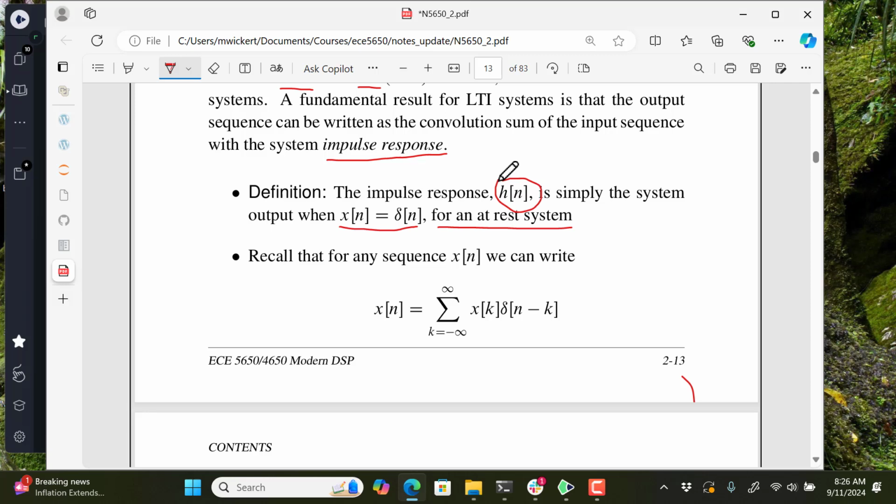Or another good idea is when your car goes over the railroad tracks or through the potholes, which we have plenty of around town, you could think of that simplistically as a single pulse like that. And what does your car's suspension system do? It reacts and you bounce up and down a little bit. That would be the impulse response of your suspension system, approximately so. A delta in the continuous time domain is an approximation to the mathematical notion of the delta function. And in the case of discrete time systems, it's very precise. So we're pinging it with this delta.